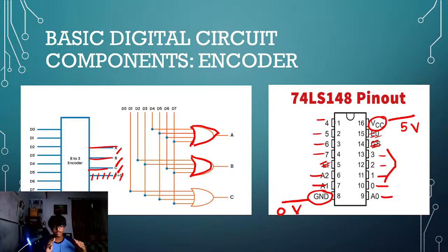You do this because you need some kind of reference for the IC. So whatever voltage difference it has between VCC and ground, the circuit merely redistributes it among the pins. In this case it's 5 volt, it takes that voltage difference and applies it to certain pins based on what you input. Is that clear? I hope that's clear, guys.